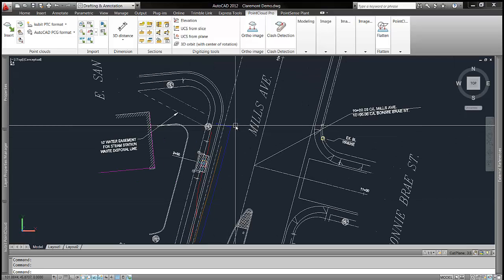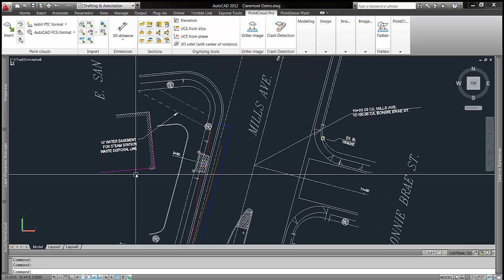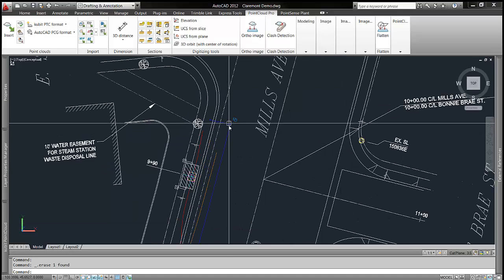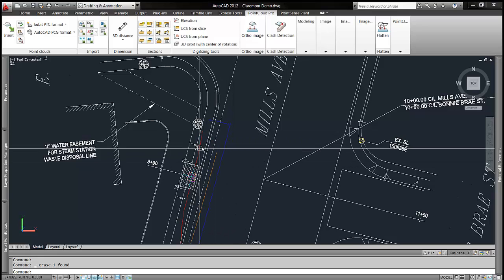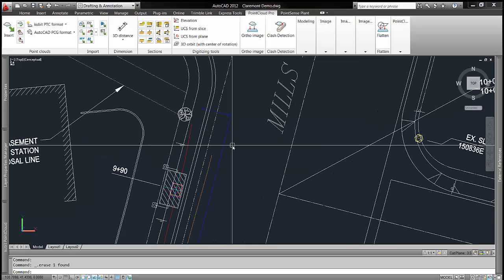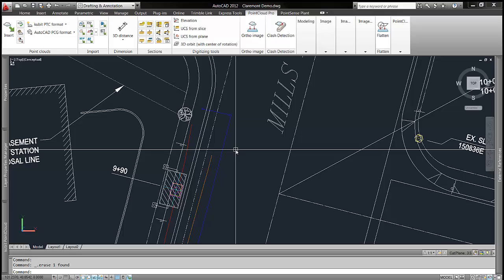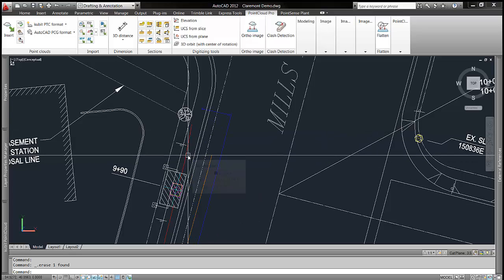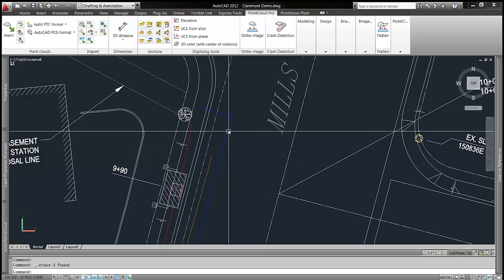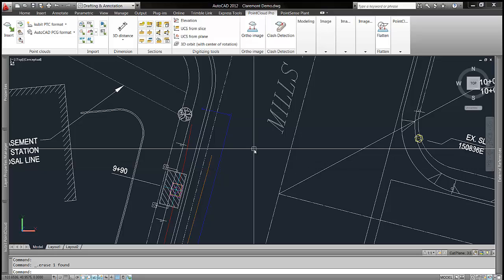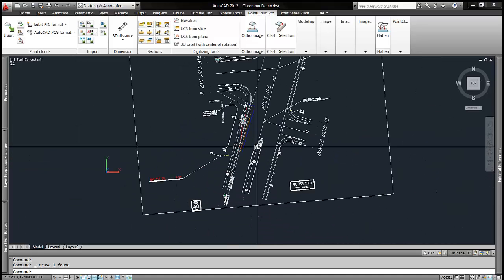You can see I've already started to process some of this information. I actually aligned a portion of a building. I'll take that out, we don't need it right now. But I started drawing in, here's a water line, here's a comm line, here's the electrical line associated with that vault. Now these lines can be as detailed as they normally are using your CAD standards or ours. Typically we do the APWA color codes, so that's why the water is blue and comm is orange and red is electrical, and so forth. Usually there are little indicators like W's for the water lines, C for comm, and so forth as well. So that can all be edited as well.